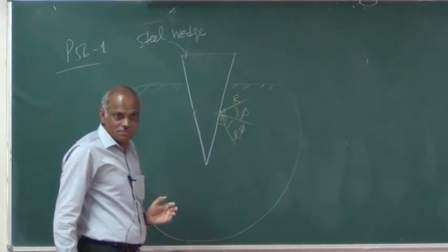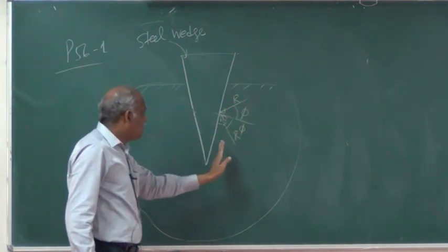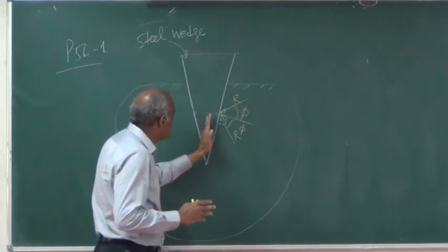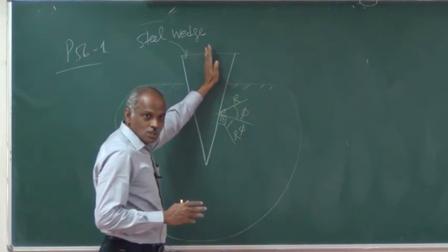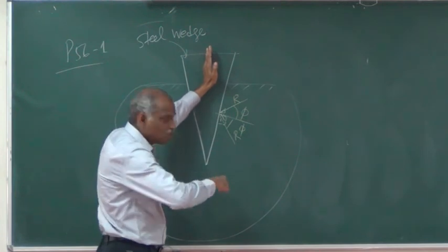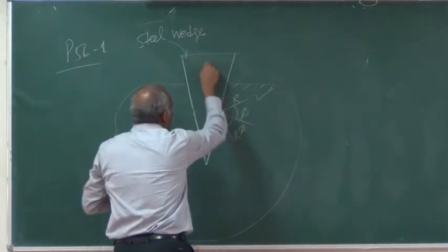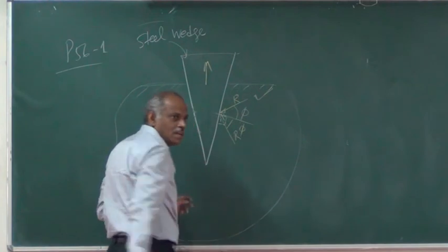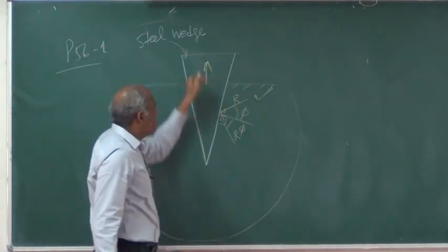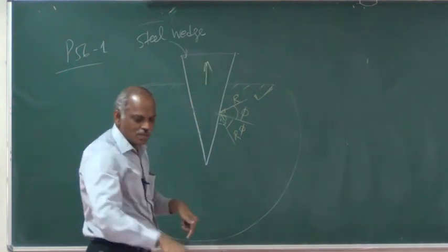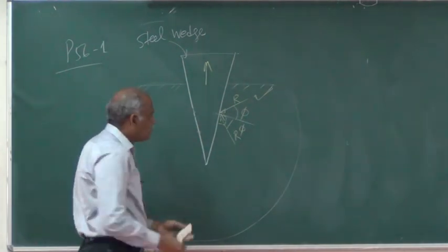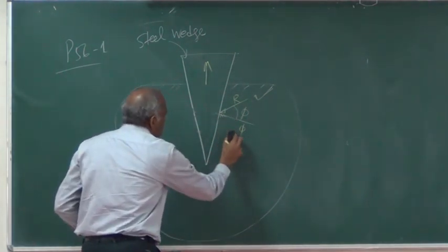way is a question. But then you have to see in what direction the relative motion would occur. So this is tending to move upwards, so the force that will be applied will be trying to resist it. So this is the possibility when the motion is upward, and this is the possibility when the motion is downward. So here, in the absence of the external force that is trying to hammer it down, the friction force will be like this. Okay, so this is not possible.